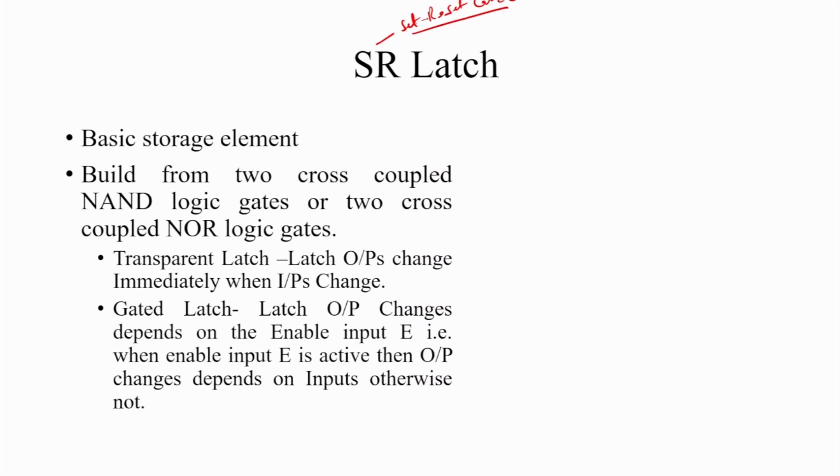Set reset latch means this is a latch, and we already know what a latch is. A latch is a basic storage element which is capable of storing a single bit of information. Gates are the basic building blocks of a latch, and when we design a flip flop, we use a latch. But for designing a latch we use logic gates. For building an SR latch, either two cross coupled NAND logic gates or two cross coupled NOR logic gates are used.